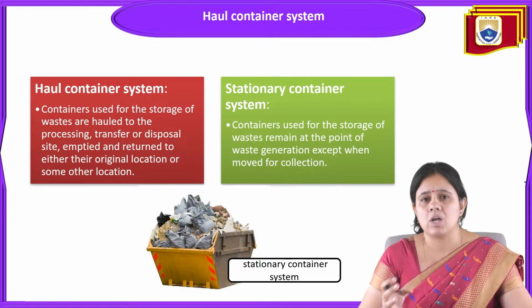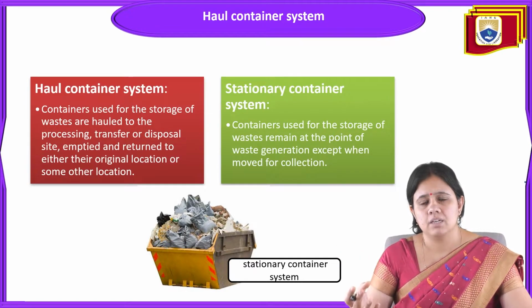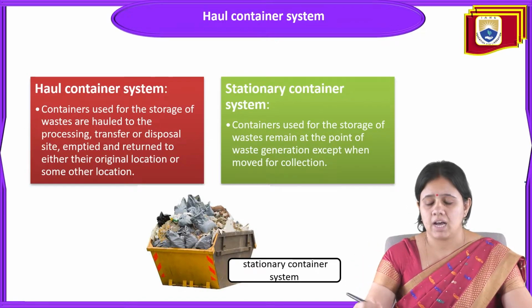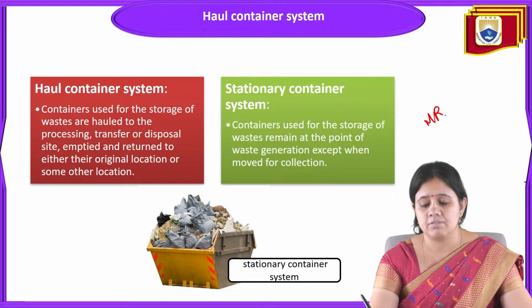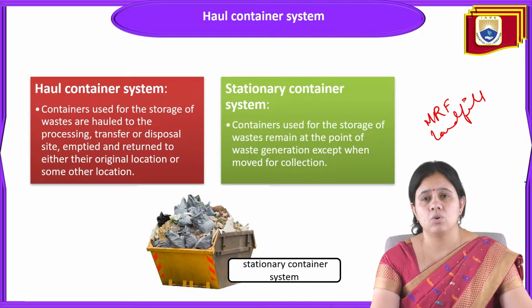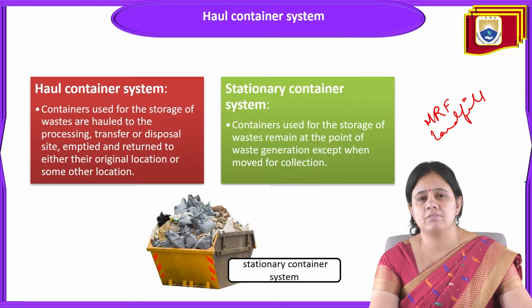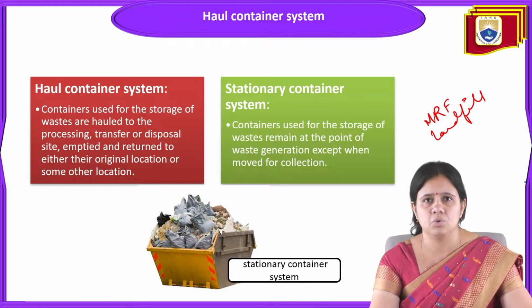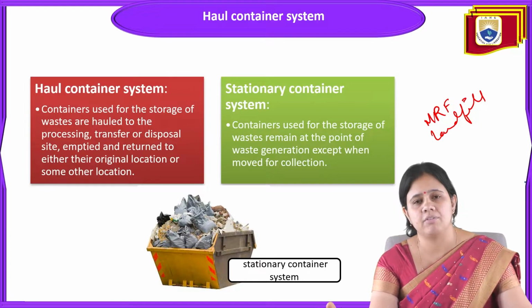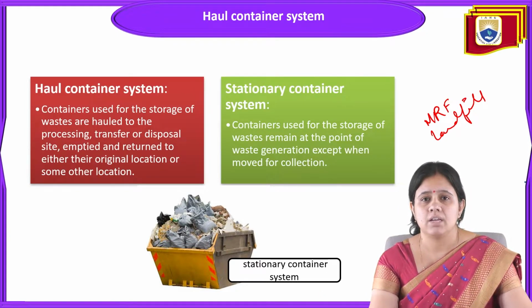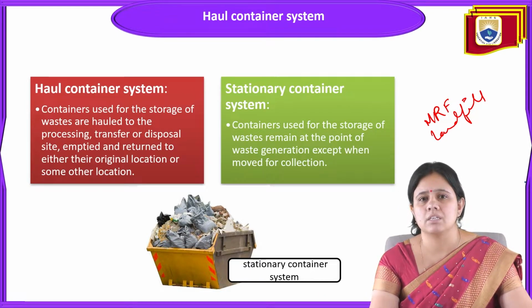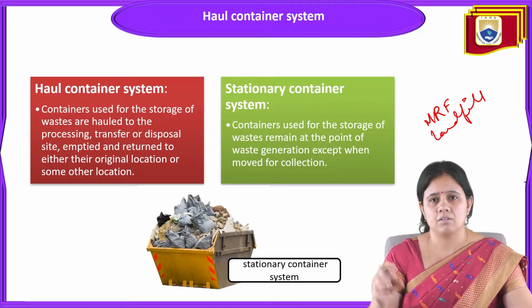What happens in this Hauled Container System? The vehicle will go and drop the waste at the facility, either an MRF, a material recovery facility, or a landfill site, or whatever it is. The vehicle will deposit that waste at the processing unit, and then come back to its original location, and then the vehicle will go to the next location. In this way, collection is done in the municipality.